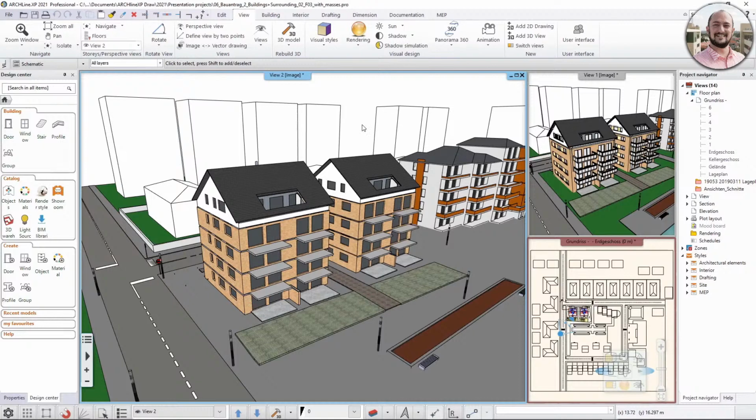And the reason could be several. So for example, if I'm communicating with another profession that does not need the fully detailed architectural model with all the layers, for example, I send over my model to an MEP designer, I can just get rid of the details that are not necessary with the default setting, and I can just export it and send it over to the MEP designer. They can make the things that are their job, their task to do, and then they can send it over, and I can place it or link it into my model to the proper location.